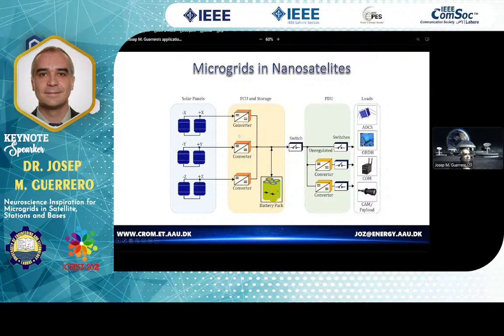And of course, control systems are also in danger because of these cosmic radiations, because protons and electrons are shooting digital systems. Maybe the digital system will hang up. This is called the latch-up effect, which happens to CMOS digital circuits. So this means that many times local controllers or primary level controllers are made with analog electronics. So it's really exciting because analog electronics are coming to the space.